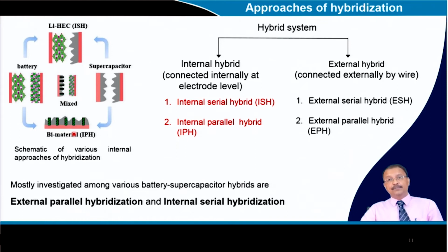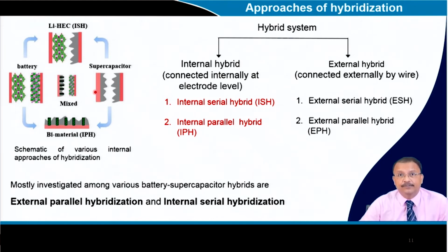Now, in parallel hybrid you mix this supercapacitor with the battery. So, in each single electrode you have supercapacitor plus battery in the same electrode. The other electrode could be a pseudocapacitor or an EDLC or a mixed type of material. So, you can imagine there are a lot of combinations available, and many exotic properties you can expect. And this is clearly different from what exactly people are doing nowadays when they run electric vehicles.